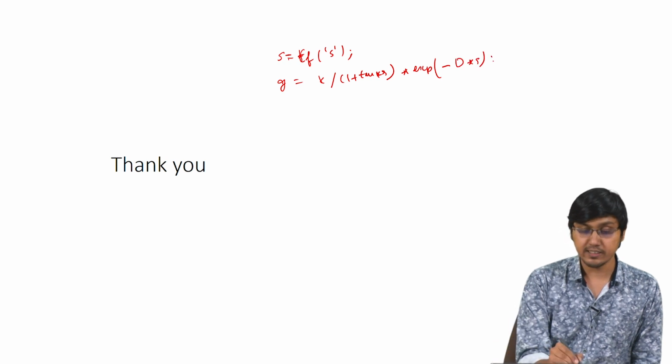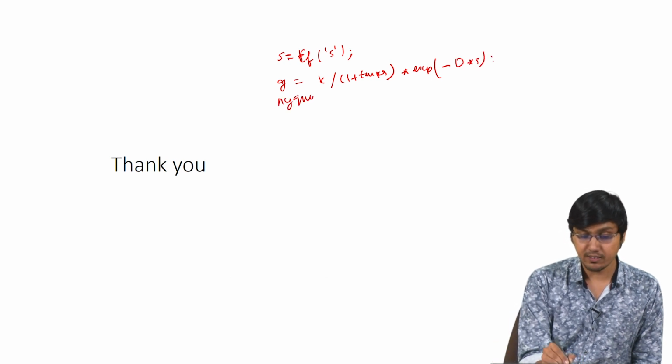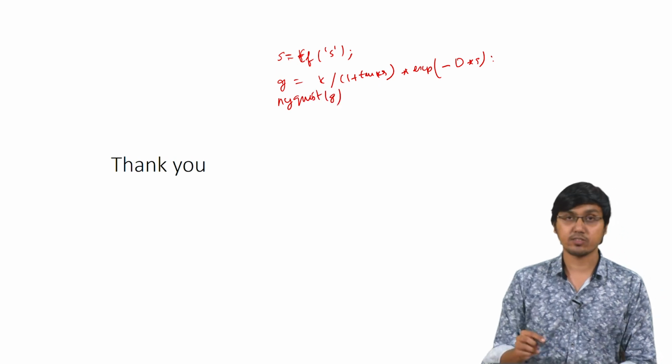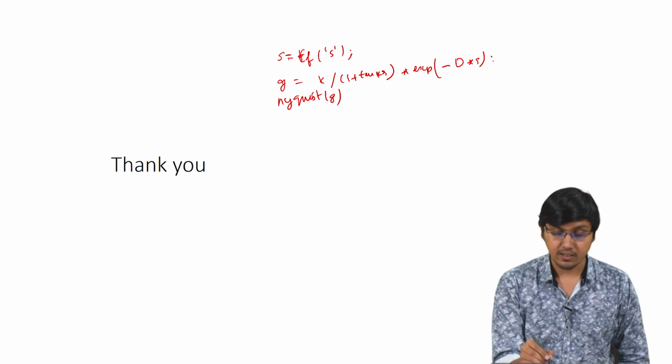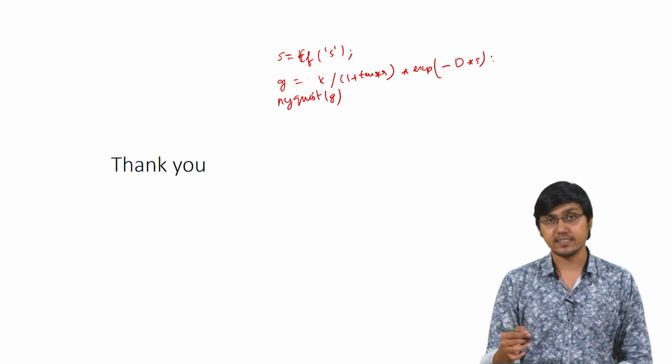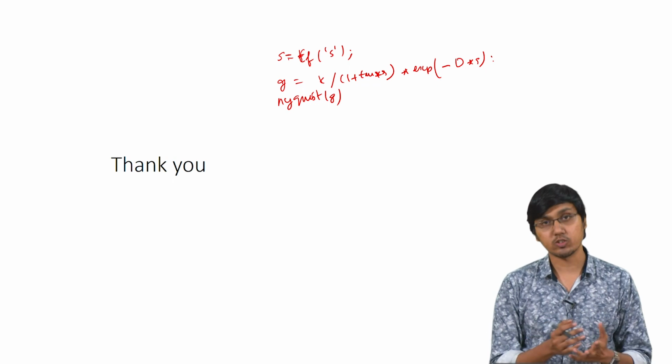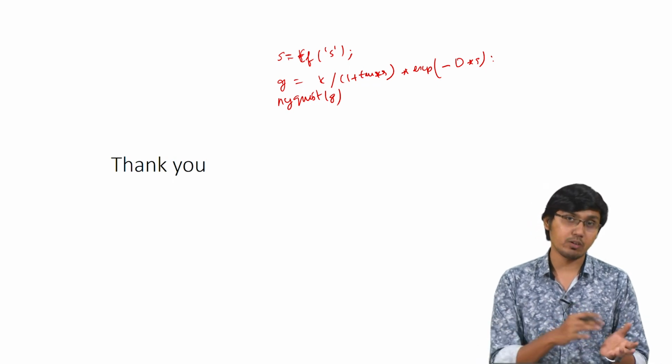Then you put the Nyquist here, plot this Nyquist graph, and substitute various values of k, tau and d to see what happens when the system goes unstable, and what the effects of dead time on stability are.